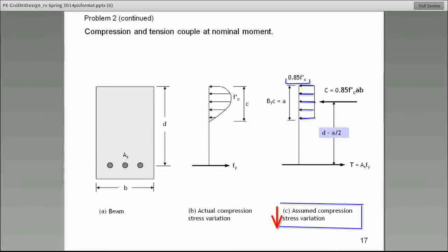Well, that area is going to be equal to, this beam is like this. All right? And the cross-section that we're talking about, this stress is acting on, is like this shaded red. Now, what is this dimension? Yeah, that dimension is equal to a lowercase a. And what about the other dimension of that cross-section that this is acting on? You got it, b, which is the width of the beam. So the bottom line is this. The area over which this stress acts is a, lowercase a times b.